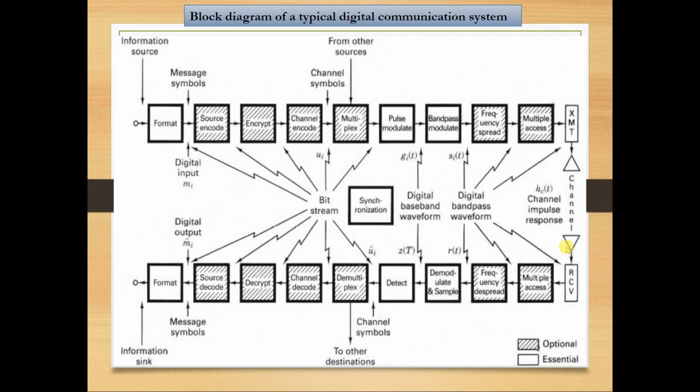This tiny amount of electromagnetic energy, once it hits the antenna, generates a current. This current passes through here, it comes to an analog circuit. The first thing that it passes through is the low noise amplifier. Your signal is extremely small and you cannot even recognize it, so the first step is to amplify it a little bit more. Give it some energy, some power so that I can deal with it. And your receiver is so powerful that it can decode the signal encoded on top of this tiny electromagnetic signal.